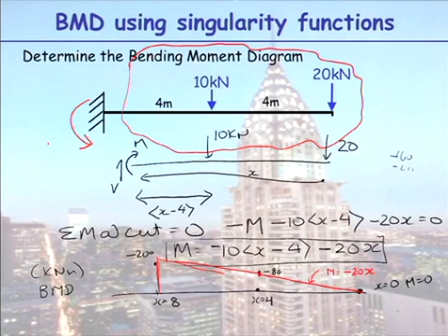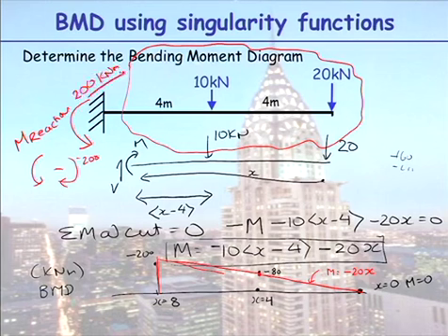If I draw a little free body diagram in here, the moment in the beam is negative 200. What does that mean? It means a sad face. So I apply a moment like that because that causes a sad face. So my reaction moment here, this is my 200 or my negative 200, assuming I'm 0.000001 mm away again, is equal to 200. So when you have cantilever systems, you can calculate the reaction moment and straight away you know the value of the moment in the beam. So I could have calculated that moment and said, okay, I know the moment in the beam is 200 as well.